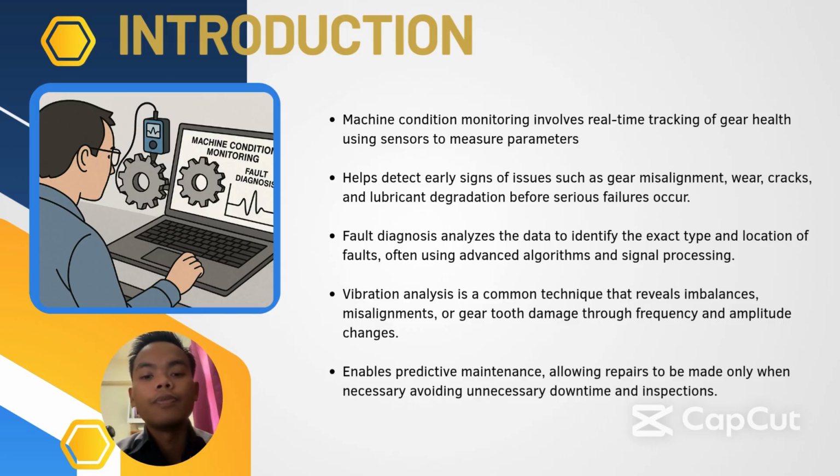into a serious failure. Fault diagnosis analyzes the collected data to pinpoint the exact type and location of the fault, often employing advanced algorithms and signal processing techniques. Vibration analysis, a common diagnostic method, reveals imbalance, misalignment or gear tooth damage by detecting changes in frequency amplitude.